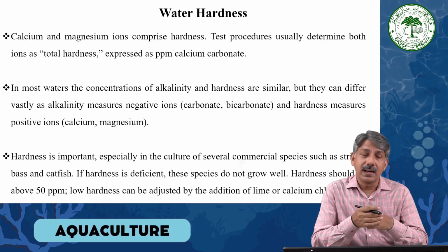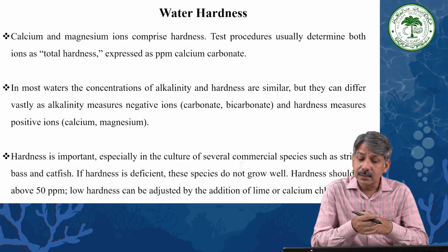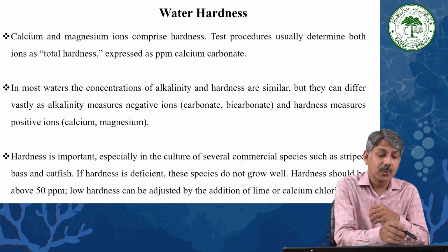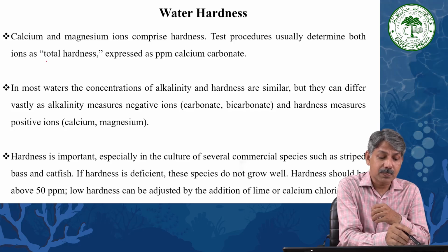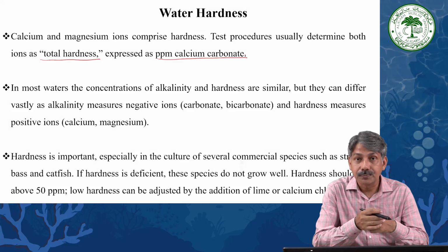Then comes water hardness. Calcium and magnesium ions comprise hardness, and the test procedures usually determine both ions as total hardness, expressed as ppm calcium carbonate.